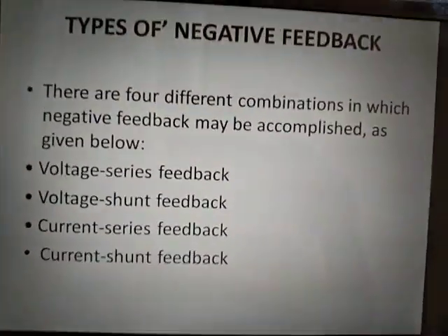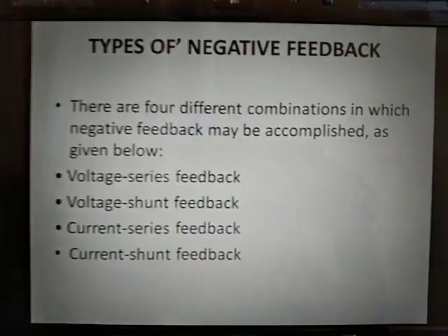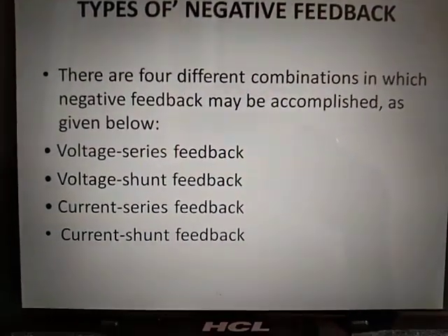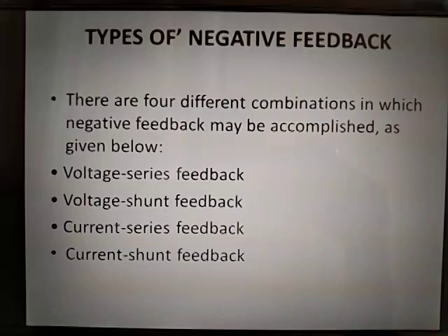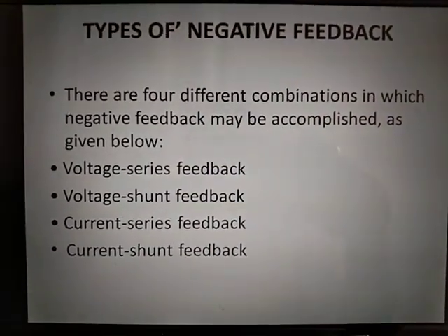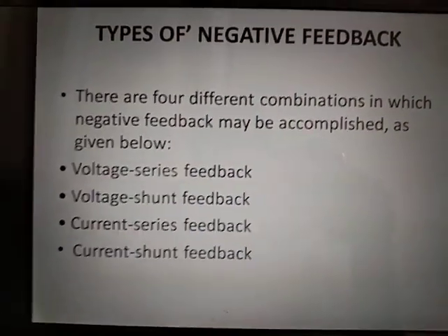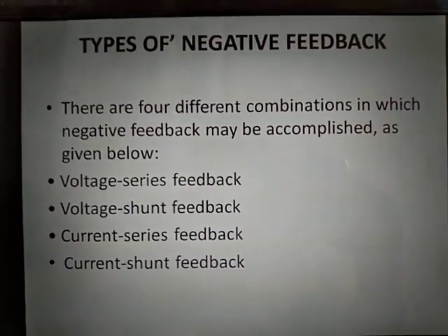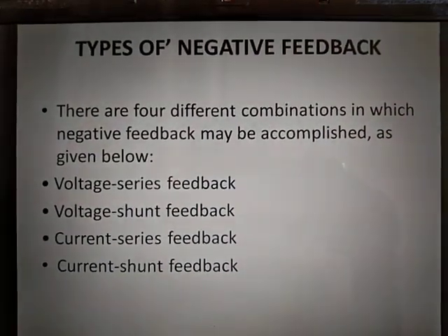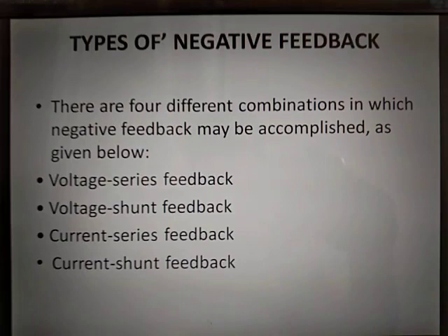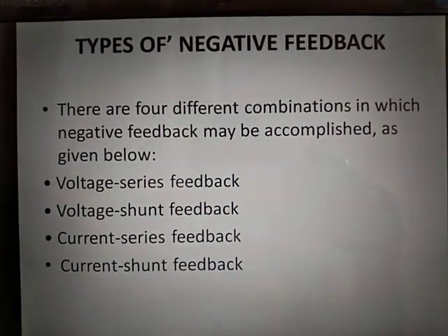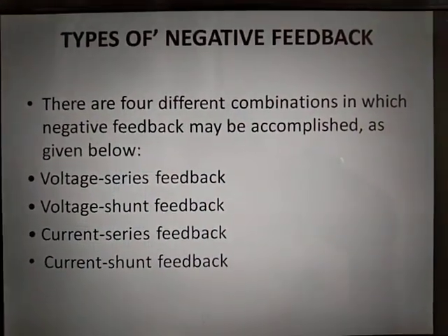Next, the types of negative feedback. There are various types of negative feedback. Actually, there are four types of negative feedback amplifier. The first one is voltage series feedback, then voltage shunt feedback, current series feedback, and current shunt feedback. Here, we are going to discuss only one, that is voltage series feedback.